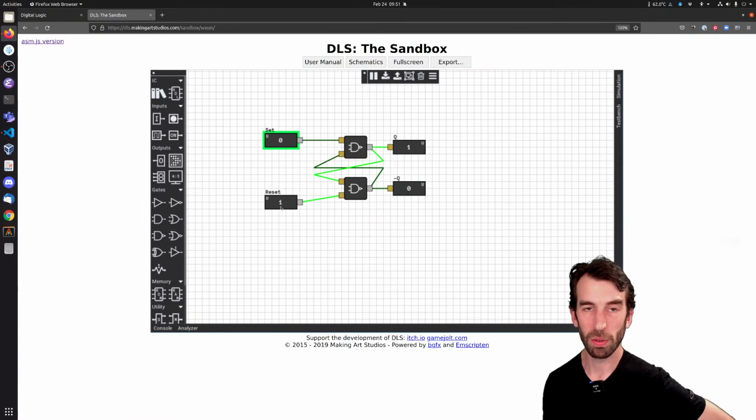Now let's talk about the other one down here. Supposing this input's 1 and this input's 0. Now this is positive input there. That one's still 1, so we've got two 1 inputs, and it's negative out the bottom. So then if I turn this one to 0, I'm doing the same thing to the bottom NAND. It's now got a 0 leg.